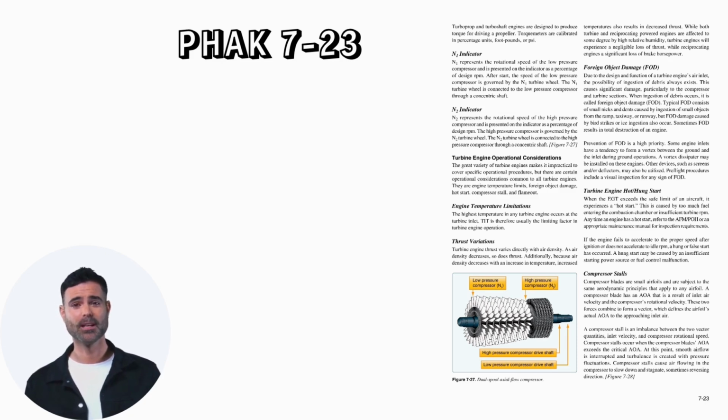Typical FOD consists of small nicks and dents caused by ingestion of small objects from the ramp, taxiway, or runway, but FOD caused by bird strikes or ice ingestion also occurs. Sometimes FOD results in total destruction of an engine. Prevention of FOD is a high priority.